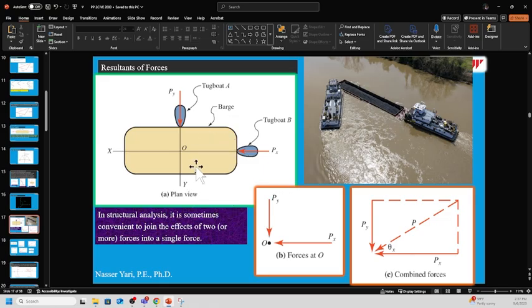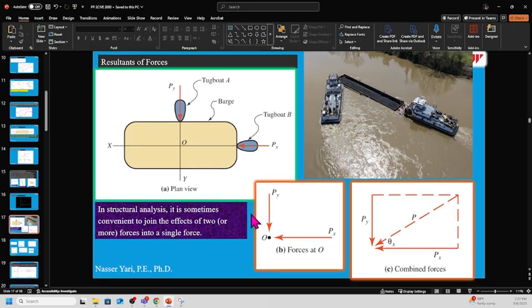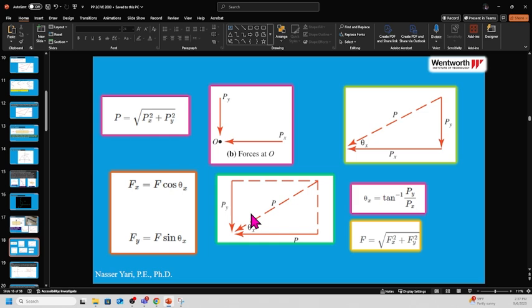So we're going to learn about this direction of the force or vector, which way it's going to go based on the angle applied and where it's applied. And what we're going to use, like last week we talked about the sine, cosine and tangent law. That's what comes in handy. And the Pythagorean theorem. So now when we look at these forces, like here, you have a Py and Px, and you want to know where this angle of P comes in. We basically say P is equal to the square root of Px squared plus Py squared. And then for the angle we're going to use tangent. Tangent always is what? Opposite divided by adjacent, and that's how we're going to find the angle. So we're going to do a bunch of examples like here.